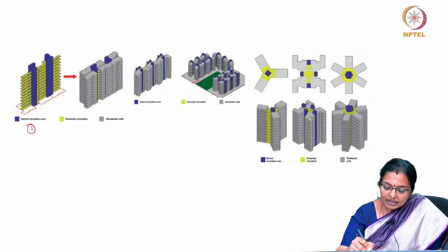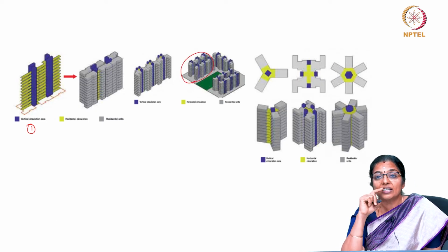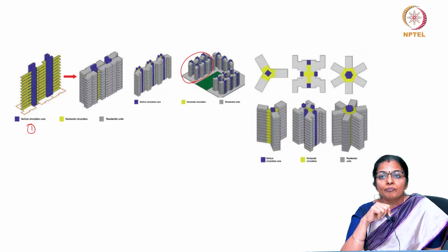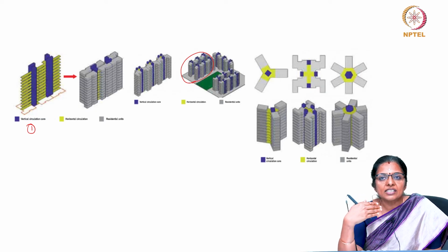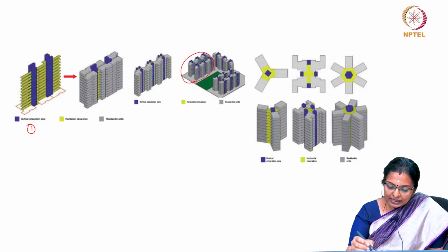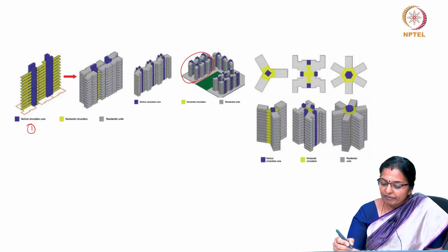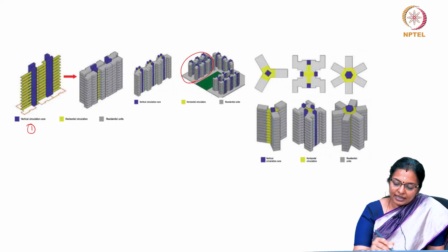This alone would probably work well with a hot dry climate, where it is very compact and massive. It has inward facing buildings. It minimizes surface areas and openings and exposure to the east and west sun, and therefore this is a good option. So, all your options must be worked out based on your climate types. We will look at each of these and analyze now.